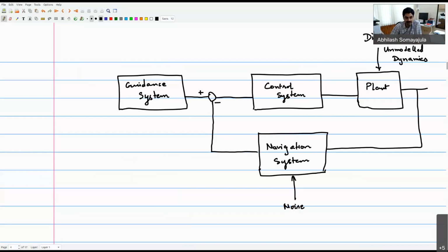So for example, I might be measuring, let us say, accelerations, velocities, and let's say it may not be velocities. I may measure angular velocity, and maybe I can measure positions using GPS. But with this, I try to estimate my complete state vector, which will include velocities, accelerations, yaw angles, all the different Euler angles and everything, right?